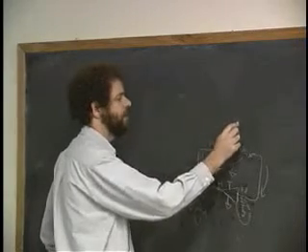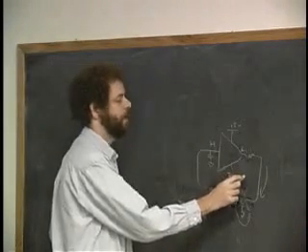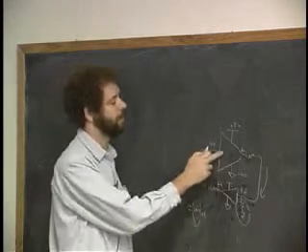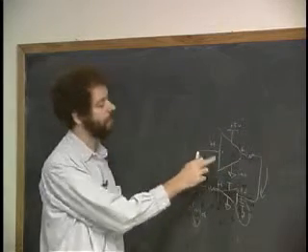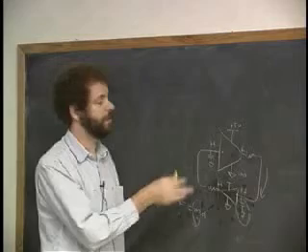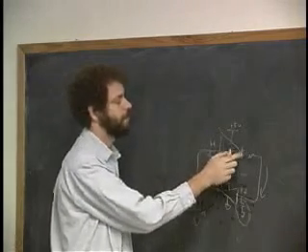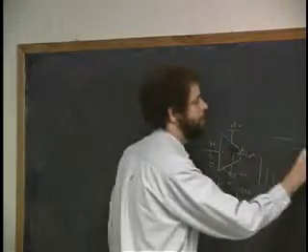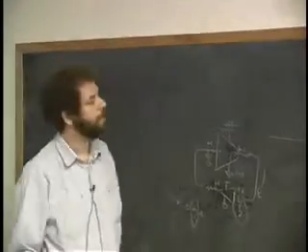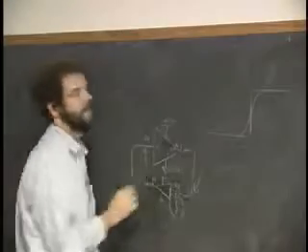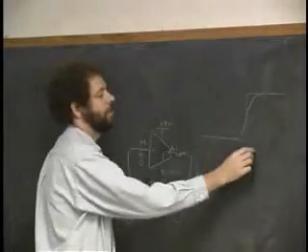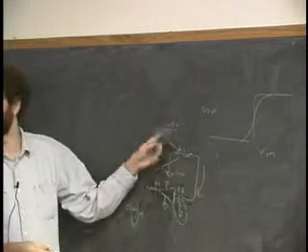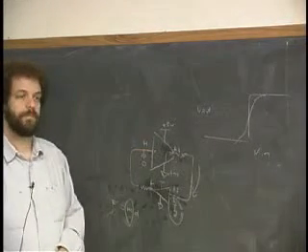Perhaps if you use a standard off-the-shelf device, it's 5 volts and ground here. And what this thing does is it senses a voltage here. In general, if it's +5 and ground, if the voltage here is more than halfway up, more than 2.5 volts, it connects this output to +5 volts. And if it's less than 2.5 volts, it connects it to ground. In other words, it has a transfer curve that tries to look like that. Now, it's non-ideal, so it has a little bit of a slope to it, kind of like this, which is again that S-shaped transfer curve between V in and V out that we talked about before, but it does it by connecting it to the power supply of the computer.